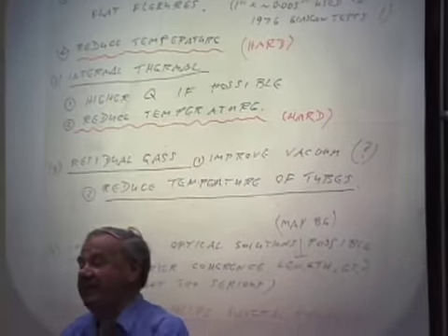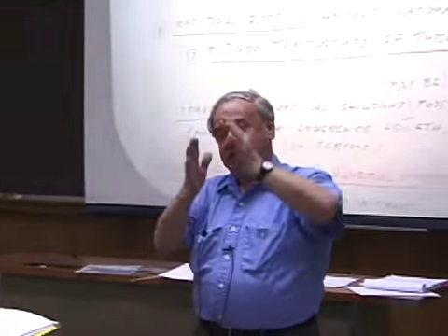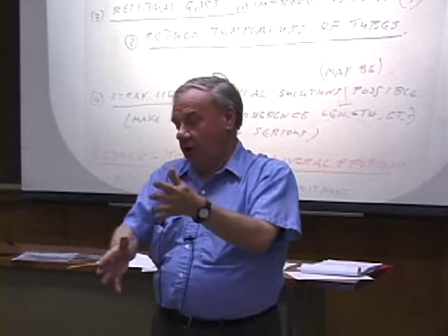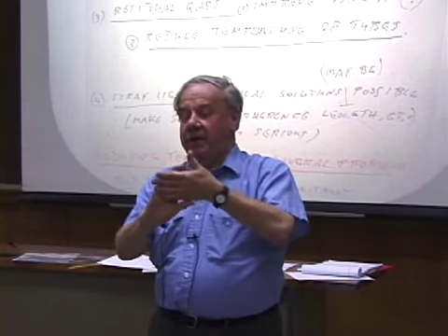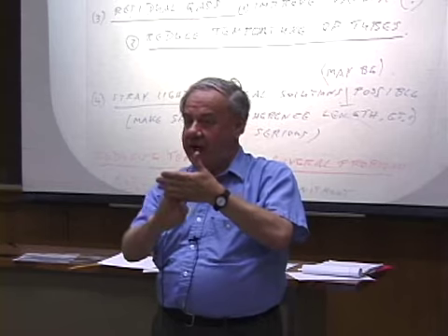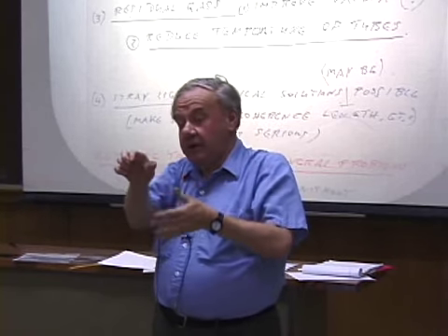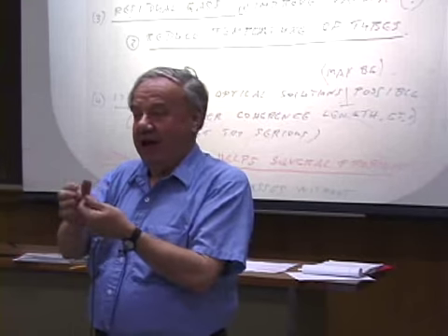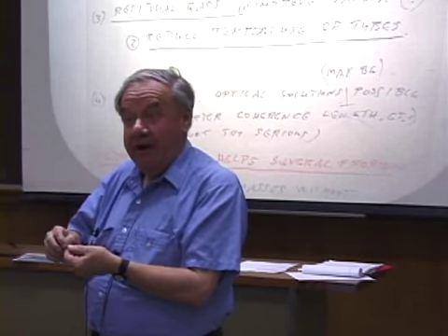But that, as it happened, had what still seems to be the very best kind of suspension. It was made on a big scale because we were hanging quarter-ton test masses, but there were actually blades of very high Q aluminum alloy that were 1 inch wide and only a few thousandths of an inch thick. And that's a very good idea.